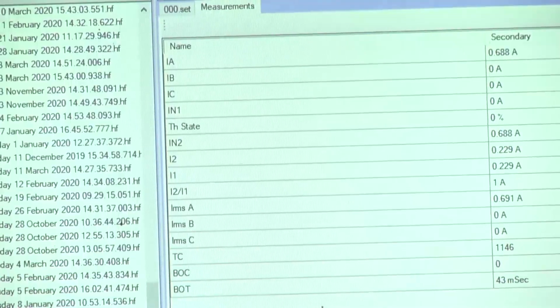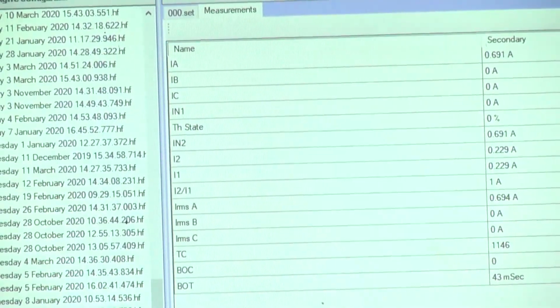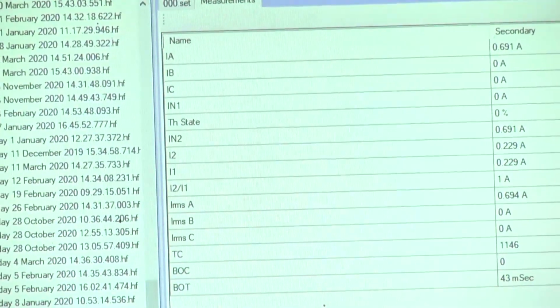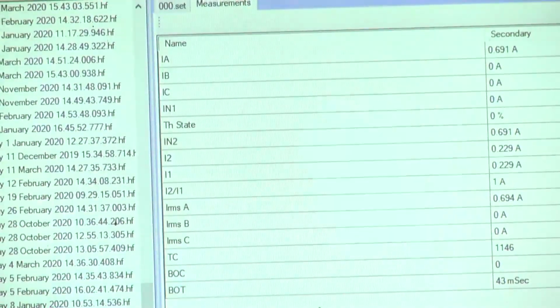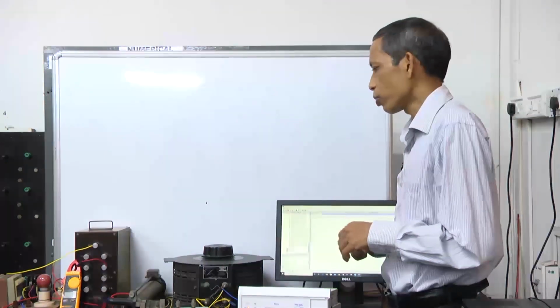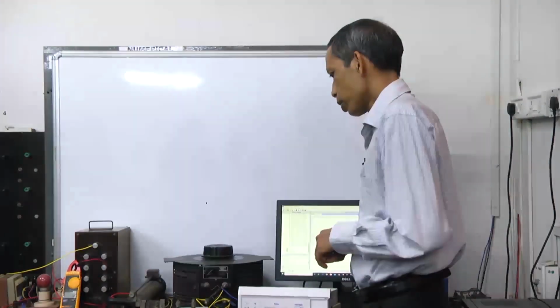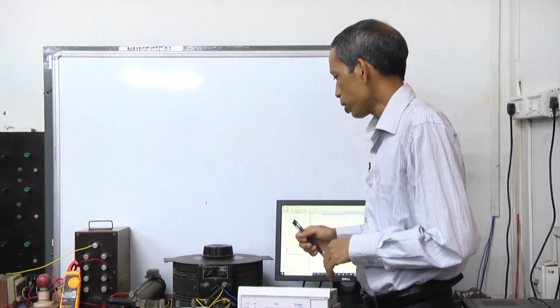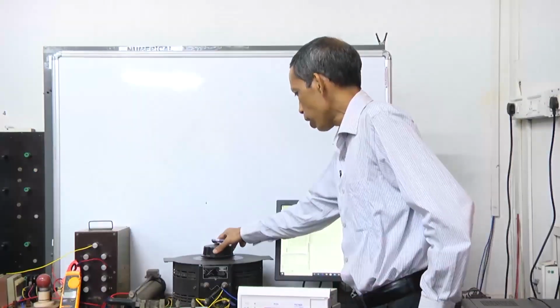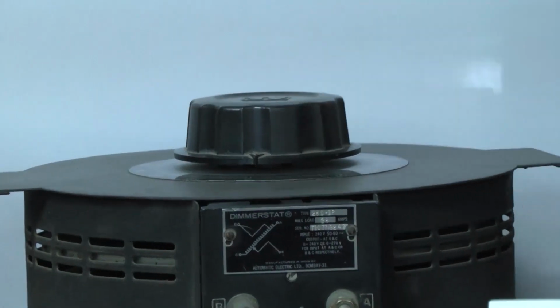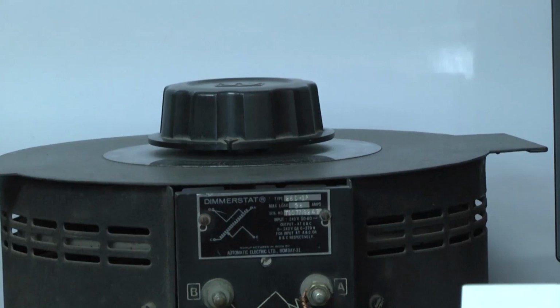Now, what we will do is create a fault, and the corresponding relay is set at 1 ampere pickup current and 1 TMS, and based on that the relay will go for the trip command. Upon this we will have the different current settings, and then the relay will go for the trip command.